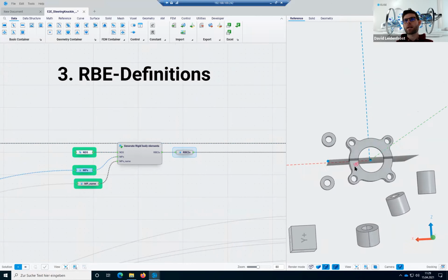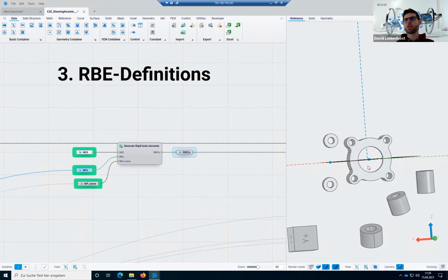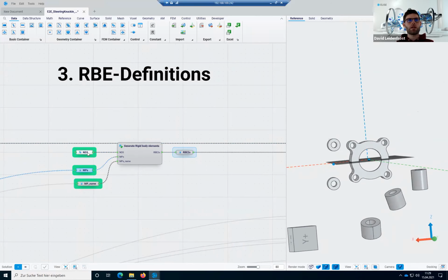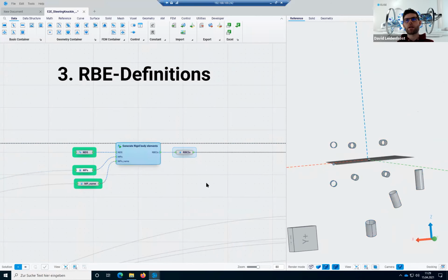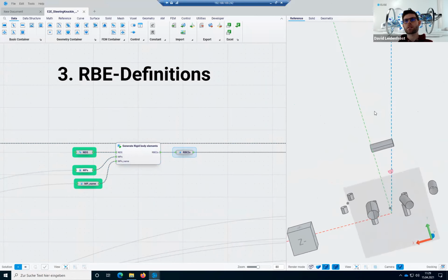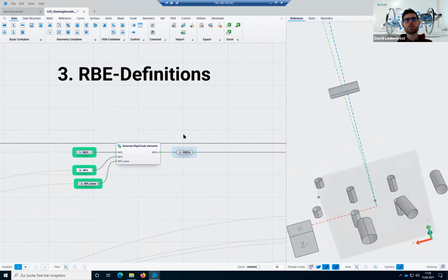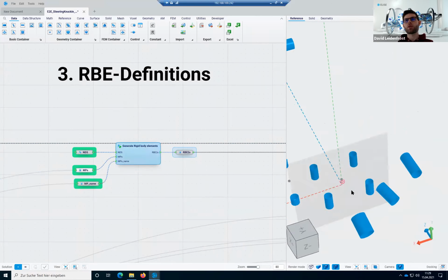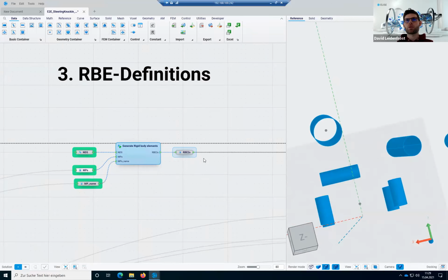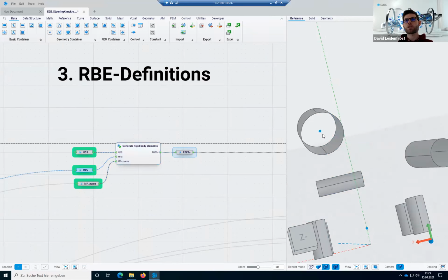And these master points need to be connected to the corresponding non-design spaces. And for that, we can automatically extract the cylindrical surfaces of these non-design spaces. And that's already it, because we only define a rule. We only define the rule, basically, that these blue master points,